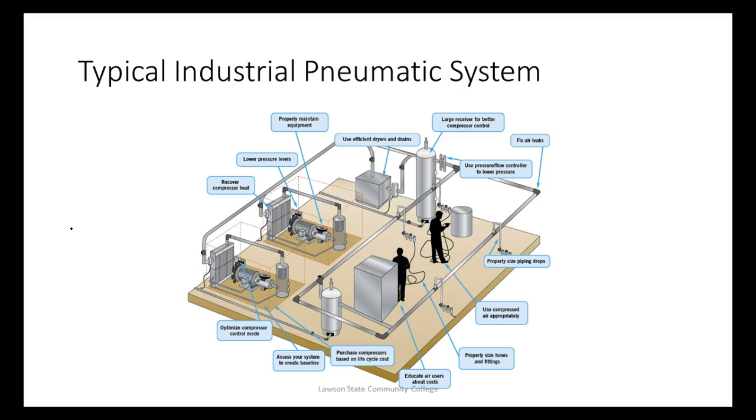Hydraulics, there's a lot of hydraulic systems. They use something called an accumulator. An accumulator is nothing but a big old tank. It's usually vertical, and it's either got a big spring in it or it's got a big counterweight in it. When you put the system on, it fills that accumulator up. It acts like it takes ripples out of the fluid, makes the fluid really, really smooth. But also, when you turn the system off, the weight of that spring or that big weight sitting up there keeps pressure on the system. This way you don't have things opening up and closing just because you turn off the pump, right? You understand?